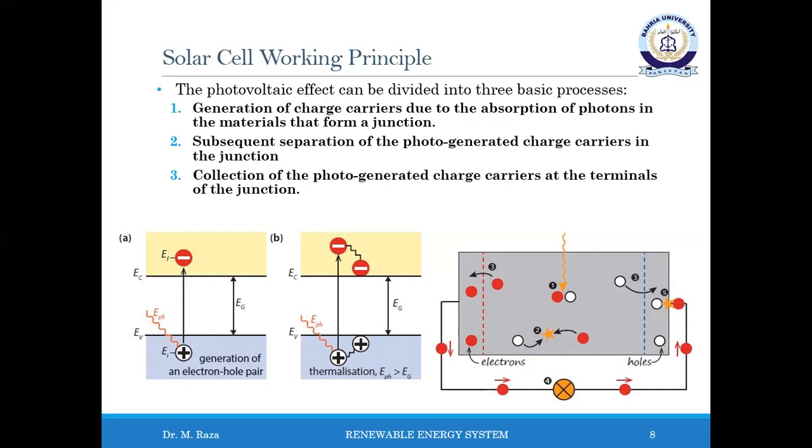Such a semiconductor is called a direct band gap material. If the electron cannot be excited without changing the crystal momentum, we speak of an indirect band gap material. The absorption coefficient in a direct band gap material is much higher than in an indirect band gap material. Thus, the absorber can be much thinner.